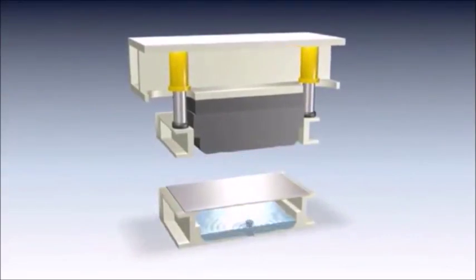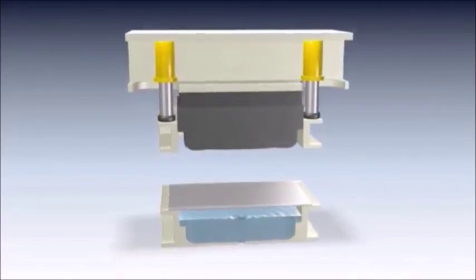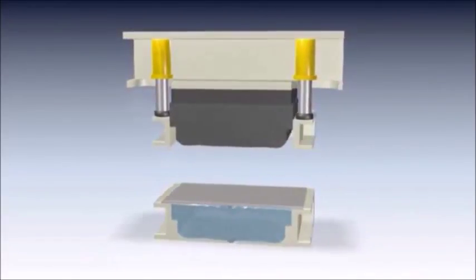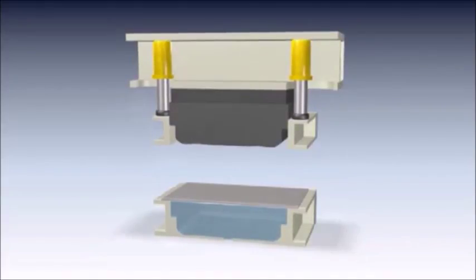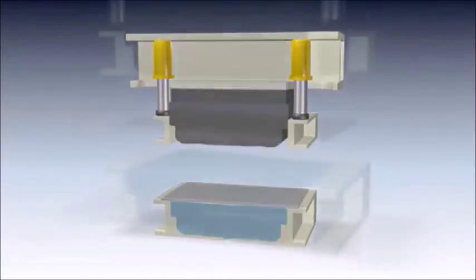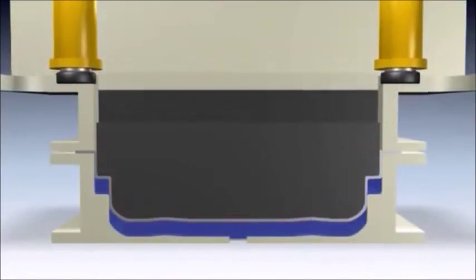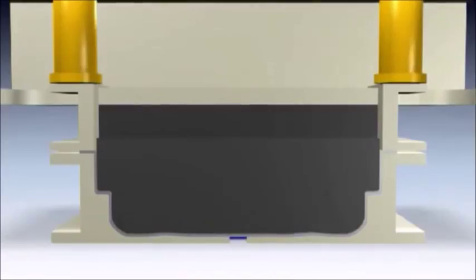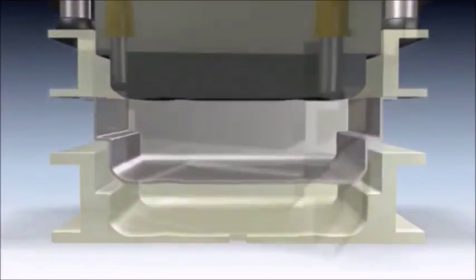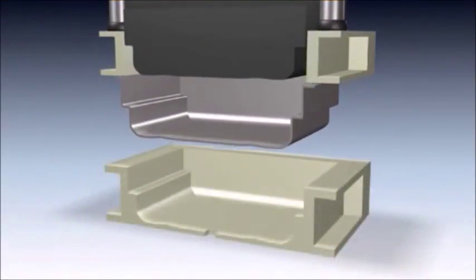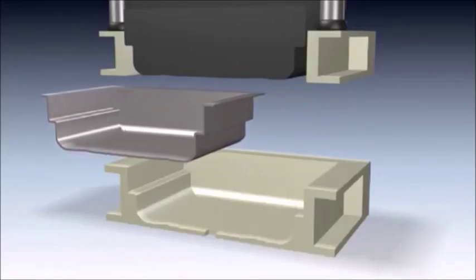Although fluid-forming presses perform the same function as conventional draw presses, they operate in a distinctively different manner. Sheet hydroforming presses use only a male die. The work of a female die to form the blank over the male die is performed by a chamber of pressurized water. By using pressurized water, forming stress is distributed more evenly throughout the part, reducing localized thinning and stress concentrations that can occur with conventional stamping, while allowing for more complex shapes and a deeper draw in a single stroke. Fluid forming is ideal for forming sheet steel as well as lightweight materials such as aluminum.